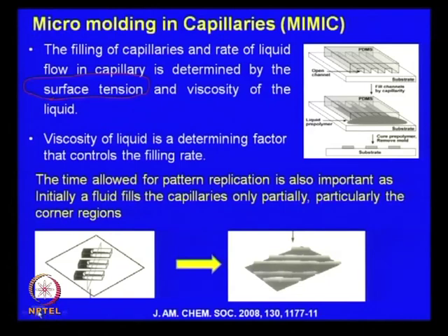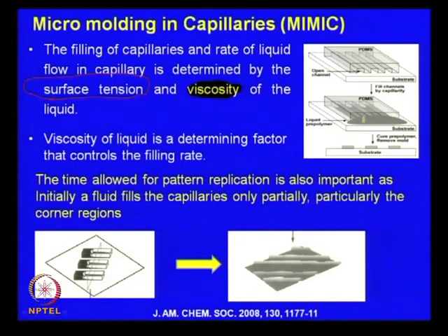Now, as far as viscosity is concerned, we need to look into how viscosity becomes important. In the simplest form, viscosity is the parameter which gives you a back of the envelope idea about the resistance of a liquid towards flow subjected to an external driving force. Here, the driving force is the surface tension driven capillarity, or a thermodynamic driving force, and the viscosity of the liquid will determine that even if you have a thermodynamically favored situation, how fast or slow the capillary filling is going to be.